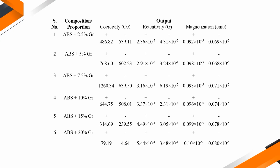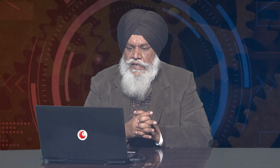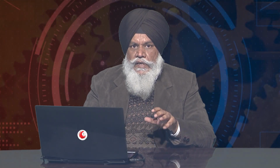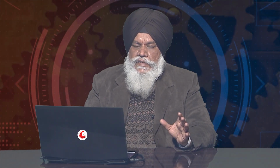We then tried to see the effect of graphene reinforcement on coercivity, retentivity, and magnetization. As I increase the proportion of graphene, there is a significant effect on coercivity, retentivity, and magnetization. Depending upon the period for which I need to magnetize the material, I can add this type of reinforcement and tune its level.